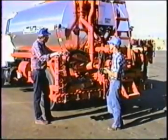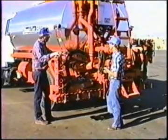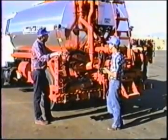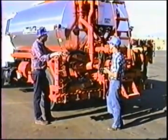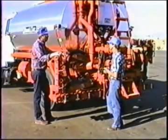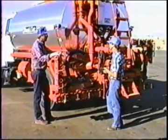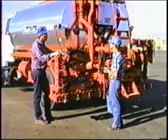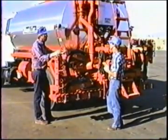All that we just went through as far as spread rate regulation manually, of course the computer does for us. If the computer's working, or if you have a machine with a computer on it, it takes care of all that. All we have to do is set into it the desired spread rate, and it does everything else.